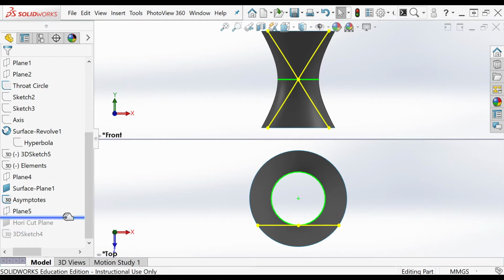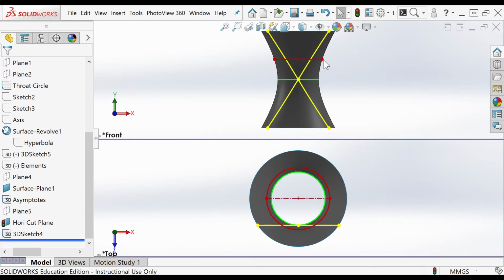So I'm going to put in a horizontal cutting plane, and that horizontal cutting plane is going to result in a circle. So this is one horizontal cutting plane. The height of it does not matter, and in plan that is going to give me a circle. So the radius of the circle, if I find this point here, I'm going to bring this straight down until it touches the asymptote. That's the radius of my circle from here to the center, and I'm going to rotate that around until it comes to here, until it comes to horizontal.